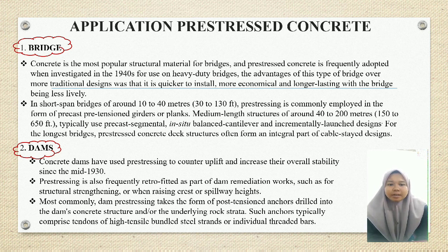Second, prestress can be applied to dams. Concrete dams have used prestressing to counter uplift and increase their overall stability since the mid-1930s. Prestressing is also frequently retrofitted as part of dam remediation work, such as for structural strengthening or when raising crests or spillway height.